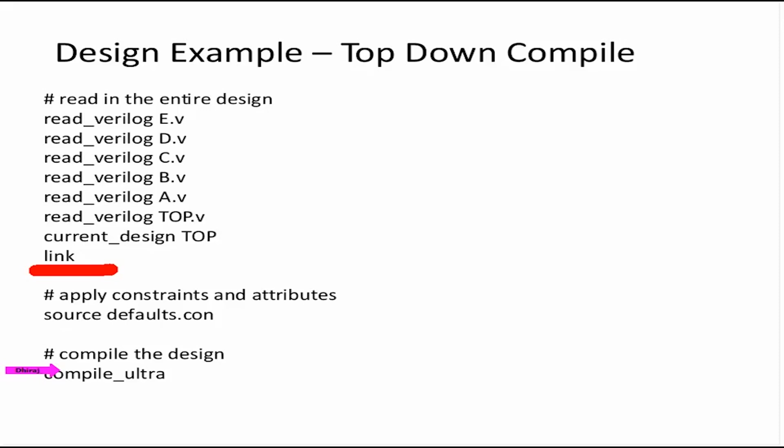You can just take the flowchart. You should just know the commands. So actually you can use this complete script as the starting point. From the slides, you can copy the script and use it to make your own top down compile script for your own design. You just have to replace read_verilog here by, let's say, the analyze command for all your RTL. Set the current design to be top, elaborate the design, and do whatever you want to do.